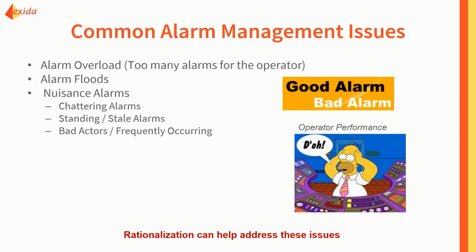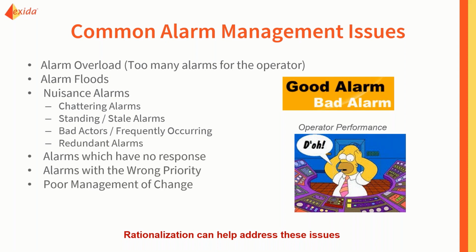effectively in that case. So you start to develop a kind of distrust towards the alarm system. And then when something problematic is really going to happen, you ignore certain important alarms, and you might get into a very bad situation. In fact, a lot of past incidents were caused by poor alarm systems.